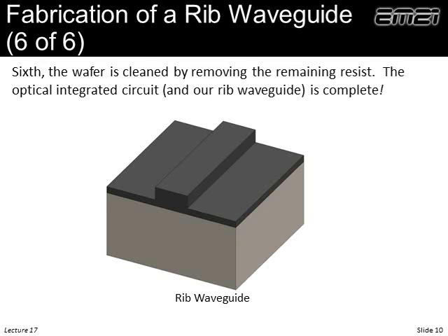What we're going to do in this lecture is show you how to generalize this so we can interfere multiple beams, and in this volume of space where they're all overlapping, we get sort of this three-dimensional speckle pattern of bright spots, dark spots. That will expose the resist, and we can form 3D structures doing that.